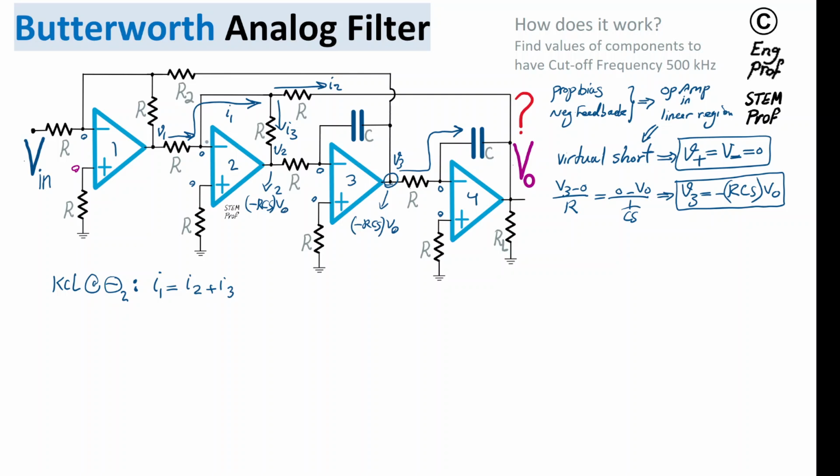When I say the negative input terminal, I mean basically this node. So if we just substitute for these values, I1 is the current through this resistor R, which is simply the voltage drop V1 minus 0 over R, and I2 is the current through resistor R, which means 0 minus Vout, since the other side of this resistor is connected to the output Vout, so 0 minus Vout divided by R. And for I3, it's through resistor R here, so it's simply 0 minus V2 divided by